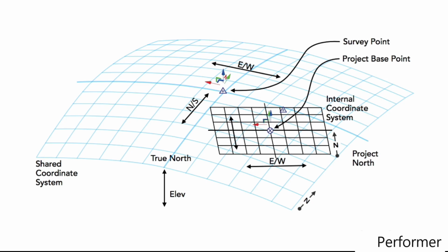So when it comes time to set up a project, I like to think of this overall coordinate system as being sort of the world at large. Okay, so that's typically your site. So whatever information you get from your civil engineer, you would relate back to that. And then placing your building on that site, your building itself becomes the project coordinate system, and it kind of sits on that site and you kind of position it where you want it to go.